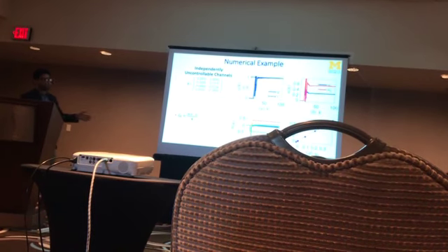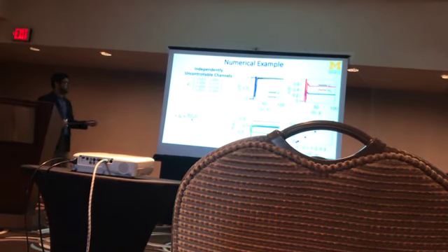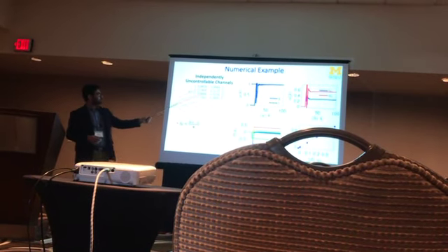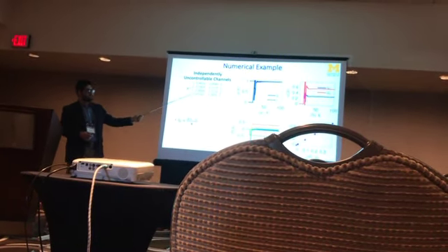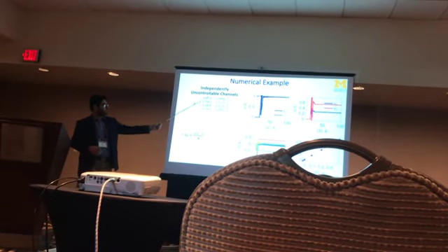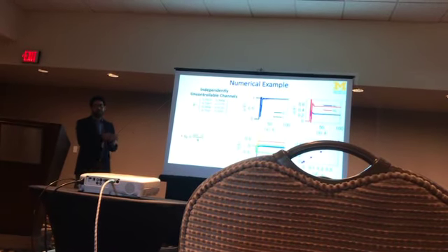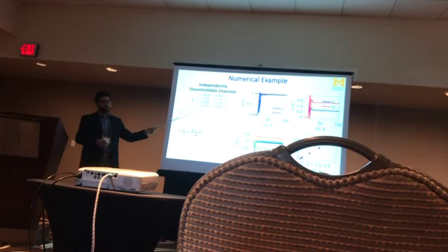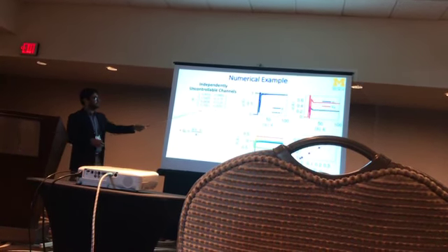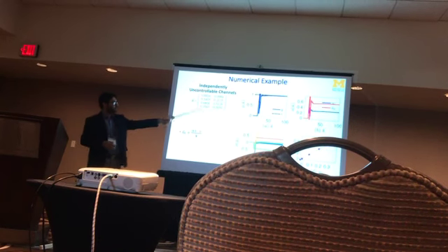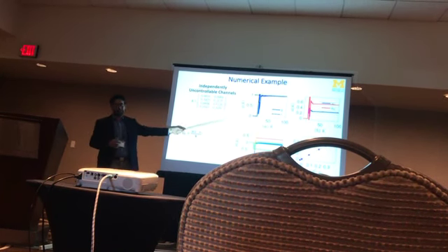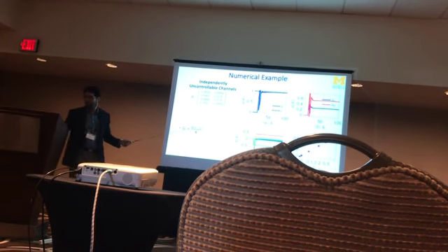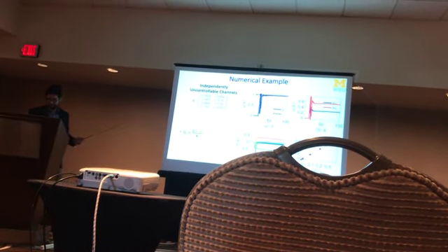Last example, these are just numerical examples that I constructed to demonstrate the idea. We choose each channel such that each of these channels independently do not give a fully controllable realization, but simultaneously they give the fully controllable realization. And in that case also exactly the same thing happens. U1 and U2 that the algorithm is computing, they are always in the fixed ratio given by the choice of the filter, GF, or the coefficient N1.